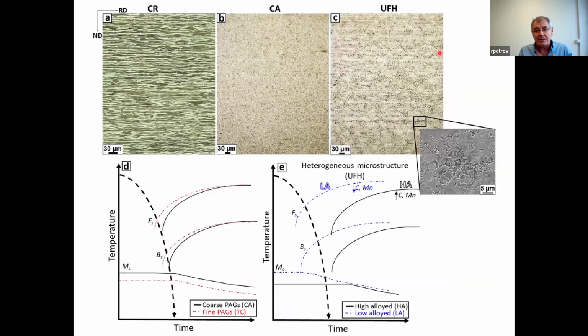If I put this schematically here, I have the initial microstructure of the cold rolled structure here. I have after conventional annealing the structure here, and I have the structure after ultrafast heating. You see, the ultrafast heating structure has a kind of pattern, which still keeps the pattern of the pearlite structural constituents distributed. If I magnify this zone, you see the story that I showed you before.